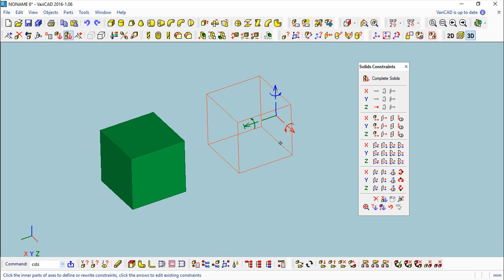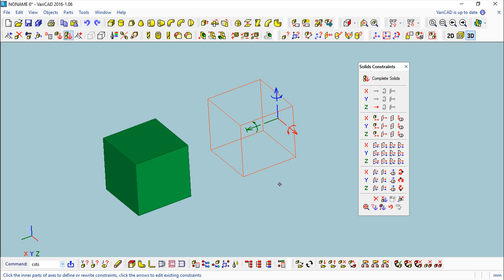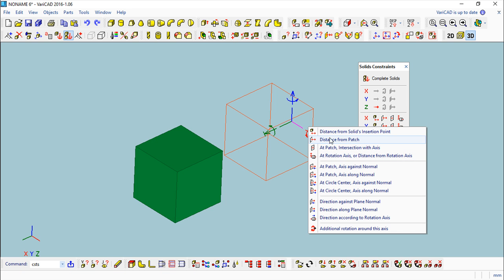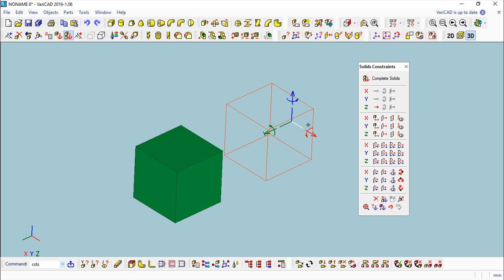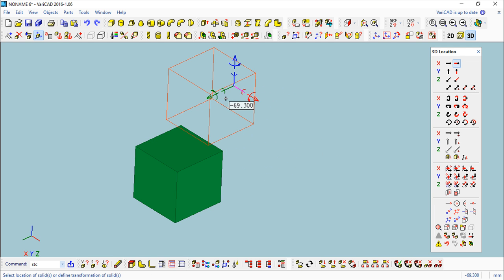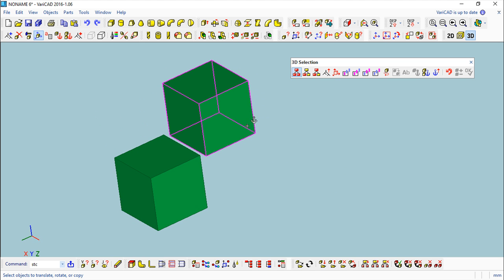For example, this is constrained, you see here as a linear movement. This is constrained in this axis, but the other ones are free, because when I try to move this object, for example, in this axis here, there is no problem, because the constraint is only on the other axis. So this is something that you should understand, that every time you take 1 degree of freedom in one of the 6 different possibilities, the others are still free.